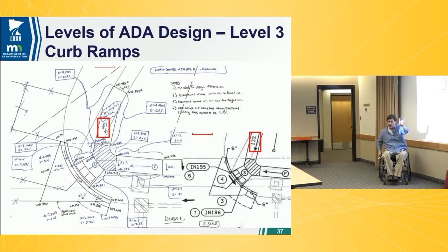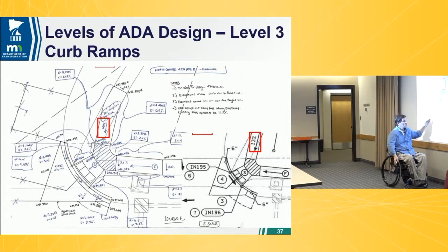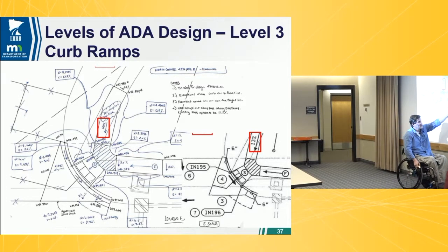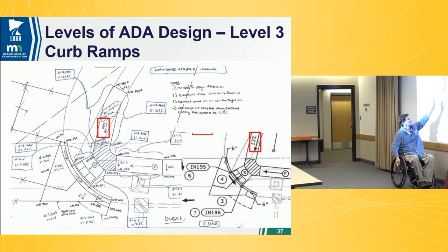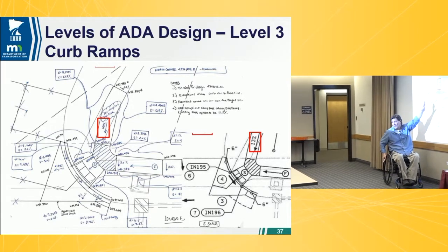So we did some design comps on this one alternate. We also looked at other alternates to make sure it was feasible. Diagonal was the best result. And again, we had gutter out, cross slope out. It was a steep diagonal. This whole area, this part along our highway, is compliant. This one is not. We had to have a 13% cross slope uphill.